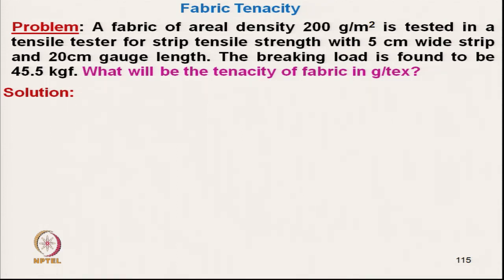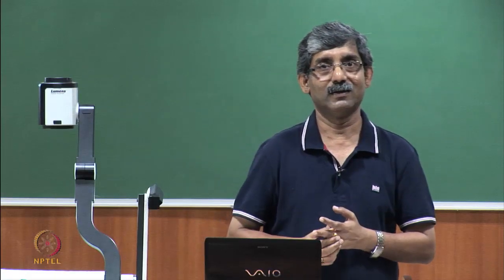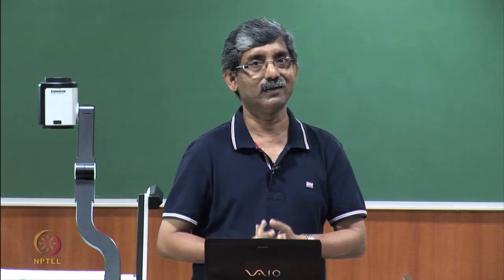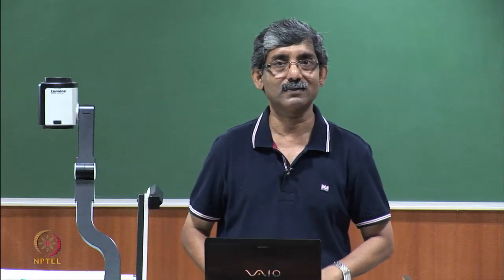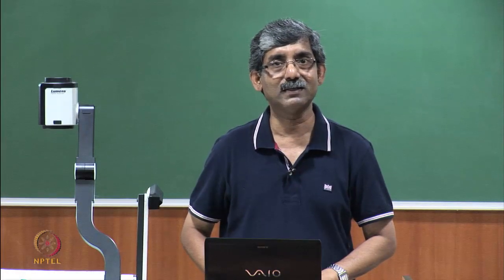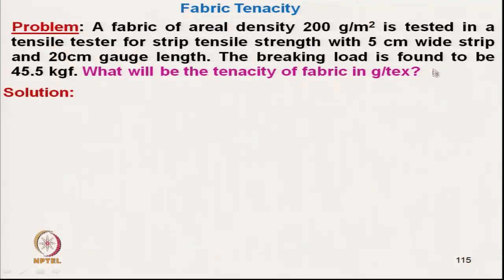Now, normally in strip test we get the value in terms of kg or Newton or something. It is in terms of load value we get, but here it is asked what will be the tenacity of fabric in gram per tex. If we see the fabric tenacity, it is normally not expressed in terms of load, it is expressed in terms of gram per tex, because